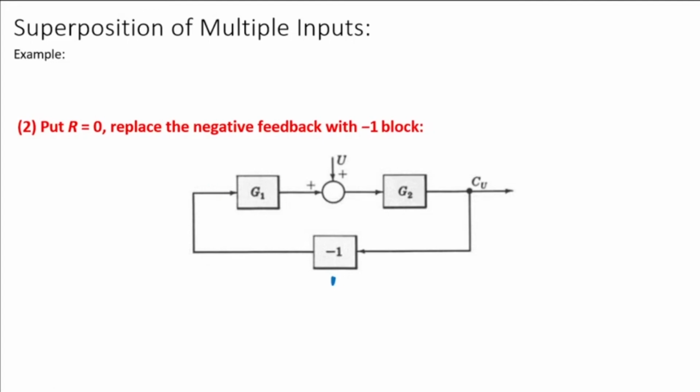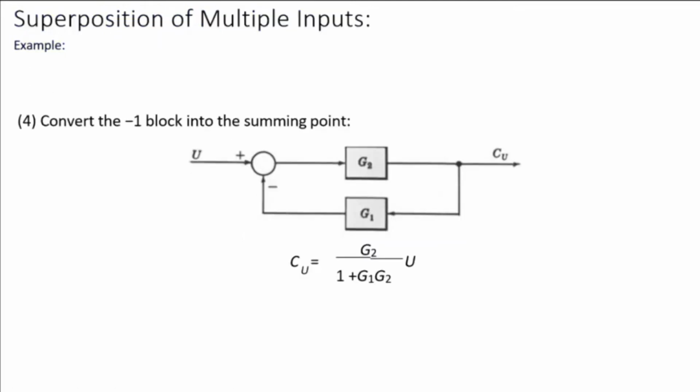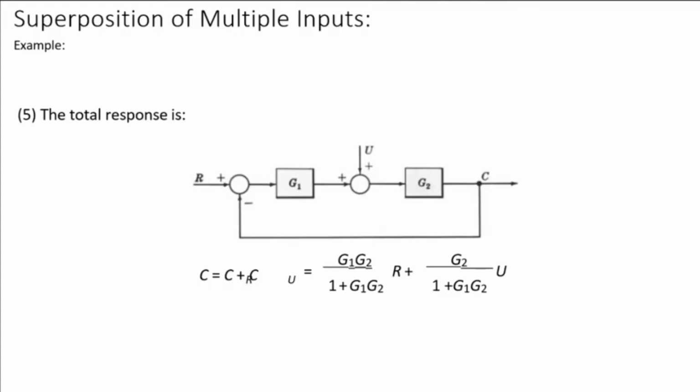Okay, so I do that again. It is very simple. So this is simply getting multiplied by that, and then we close the loop. If you close the loop, what you get is this one. So this gets multiplied by this, and then it's a G over 1 minus GH transfer function. So what we get is this one. Basically, we get two transfer functions, and based on these transfer functions we are adding both of them.